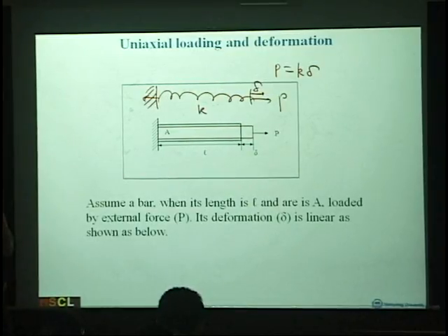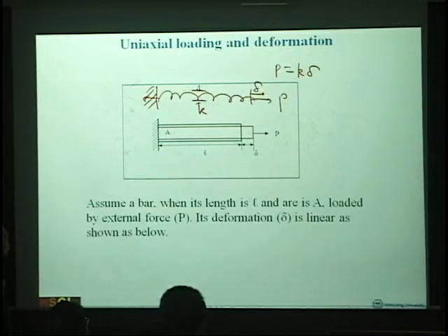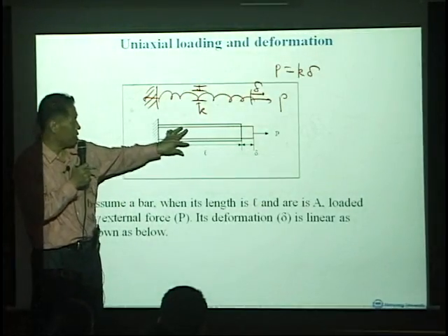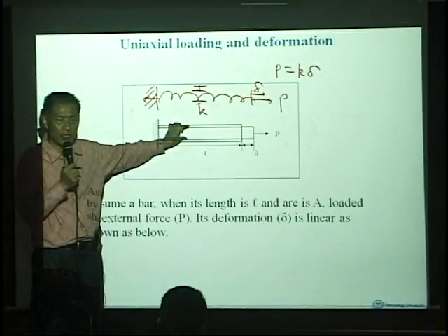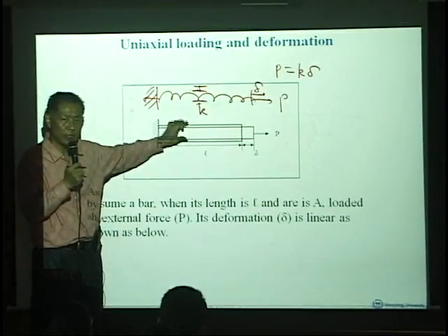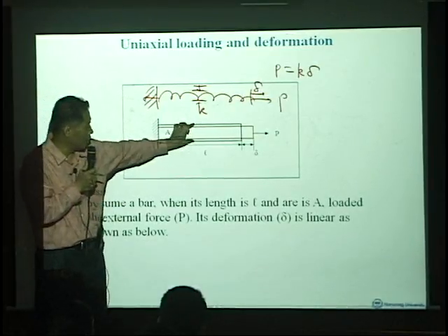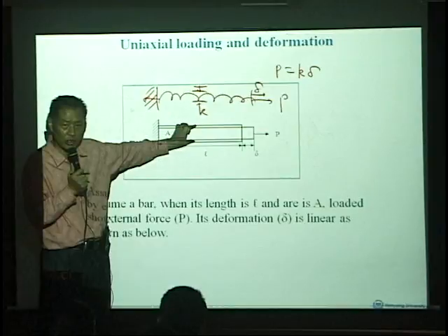That's just K. In a spring, we don't care about transverse contractions because the spring always works for axial deformations. But in a bar or solid, these contractions play a really important role in the stress and strain distribution inside the body. So we have to define a material property.